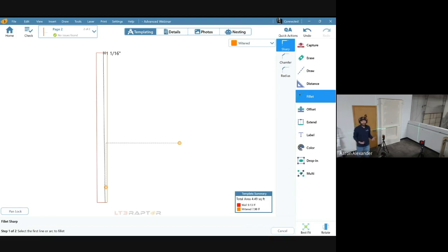Right. We're literally going to use this laser to install thousands of dollars of stone. Many fireplaces we run across, we're going to use this one laser to calculate this level and plumb and everything in space. So you really just want to pay attention to what the tolerances are. Right. We buy equipment based off tolerances, based off its accuracy. That's what we bought our laser for, right? So this thing, you know what I mean? We're going to want a highly accurate one.